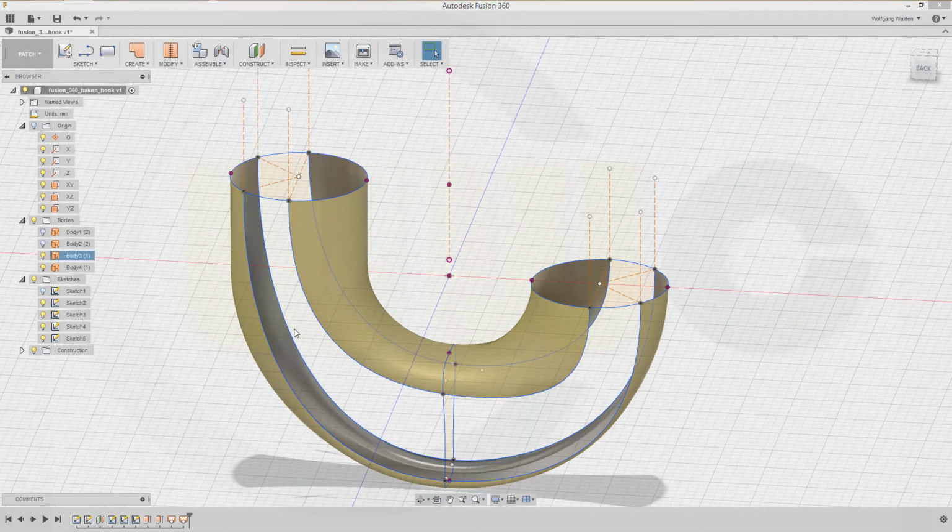Now you could do the loft with these sections and these two rails, or the other way around, use this one as section, that one as section, then you can make a nice tangent, or even better surface. Or you could use this as section, that as section, and these three as rails, and I will go for this option. So let's check it out.